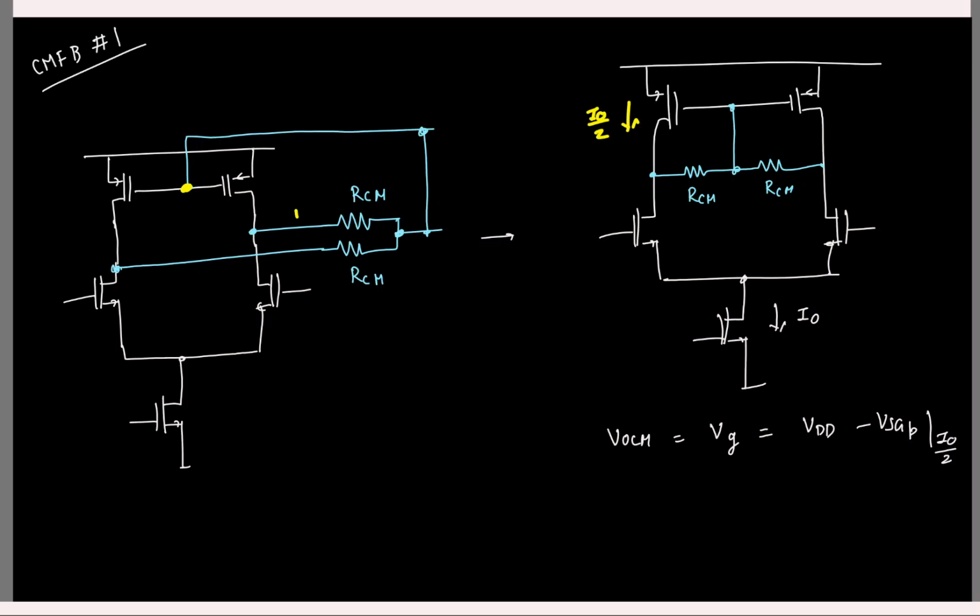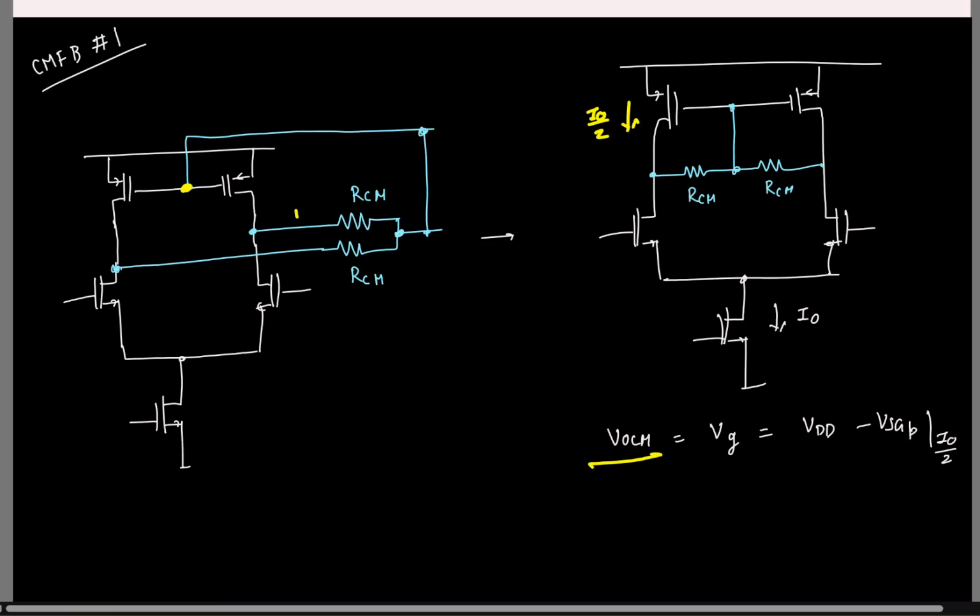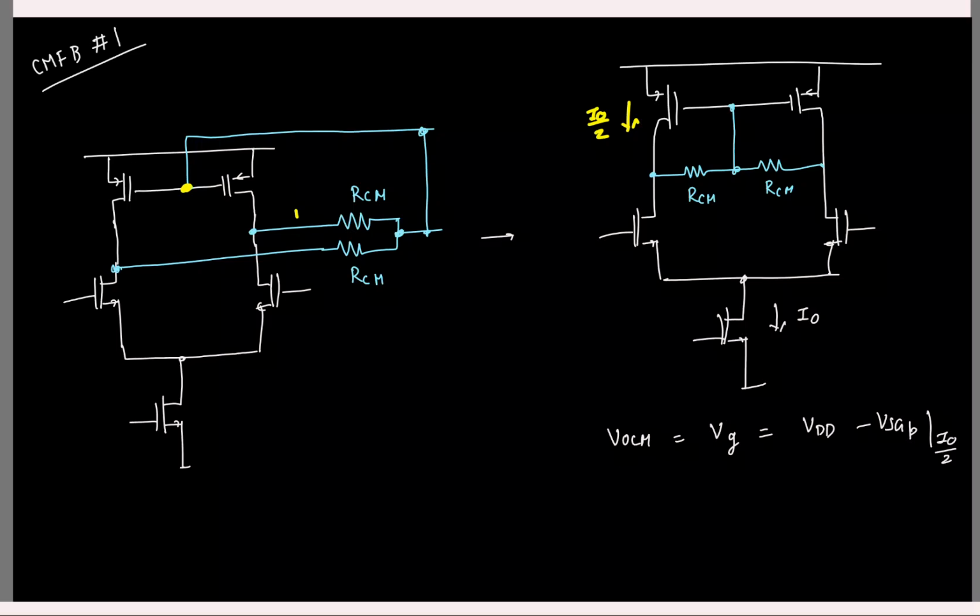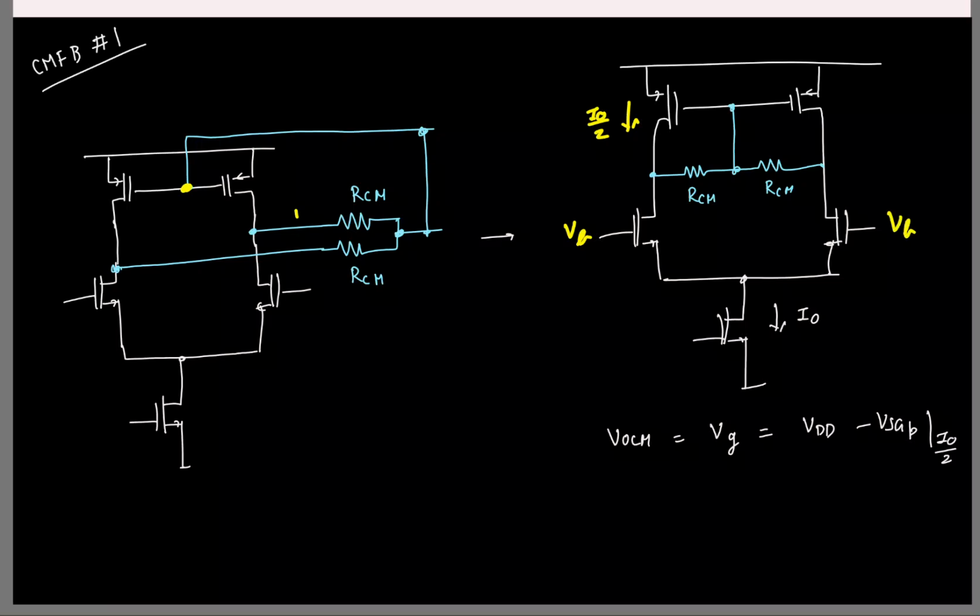Again, you can also understand this by doing the following. Now I am interested in only the common mode signal, the common mode output. So what is the half circuit I can look at? Now everything is equal, right? It's some DC bias here, say some VB. It's all common mode signals. What is the equivalent circuit I can draw? I can draw the common mode half circuit.